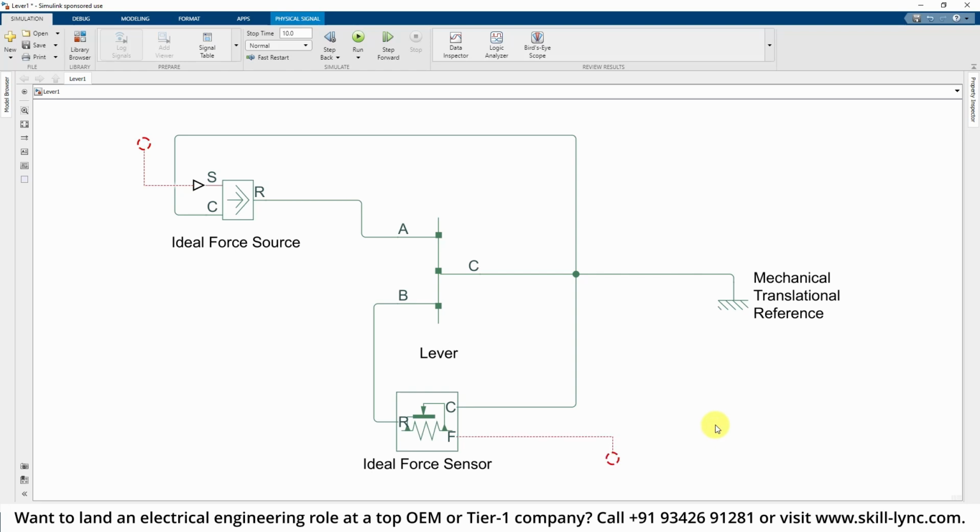So then logically it's not correct, but MATLAB will not show any error. This is going to be the error generated by the modeler itself, or the person who is going to create the model, right? If it were a green-type same signal, we could have been able to connect to this place, right? But that may not work in our example, or it is going to be logically incorrect. So syntax-wise, the model will not allow you to make any syntax error, and therefore it's going to be more clean, right? But you may have some different errors which you are not able to have visually available as this one.